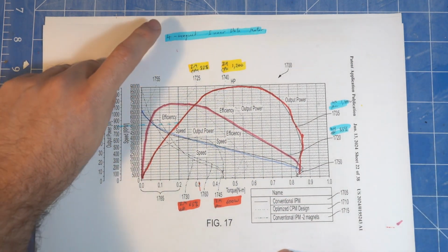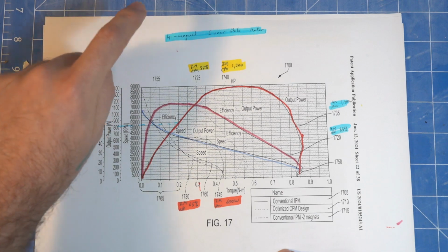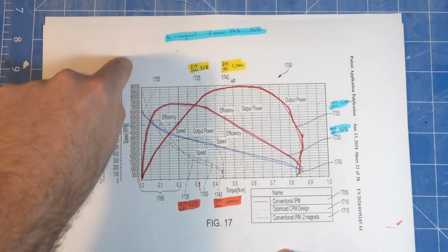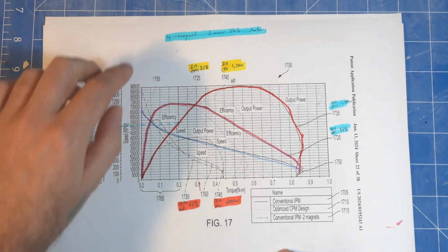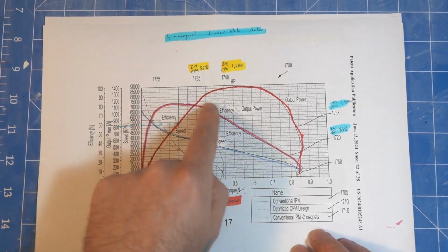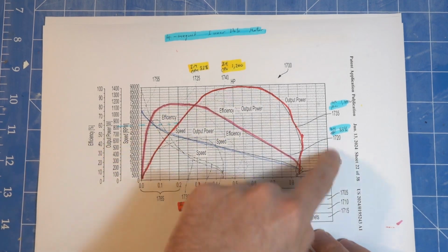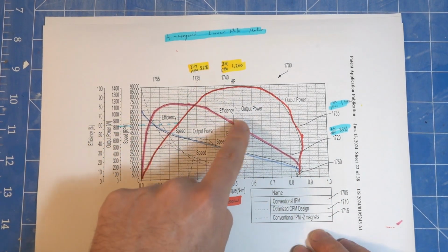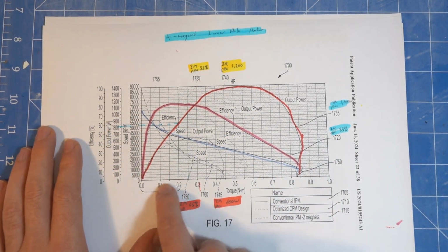I think the rest of the graphs now are all inner pole motors, or an Inrunner. This one's your very standard 4 magnets on the inner part and then 6 coils around the outside as the stator. And the Consequent pole motor gets relatively similar performance. Doesn't quite get the same peak power, but in the operating region it's about the same power and efficiency.